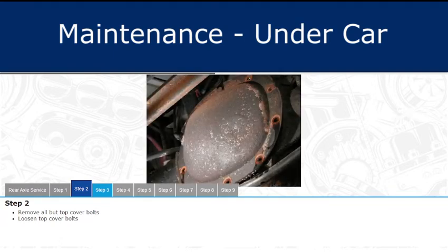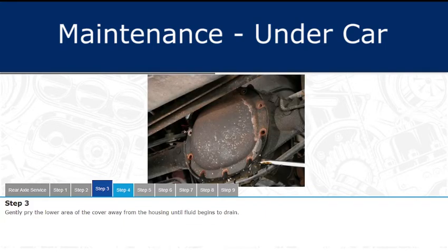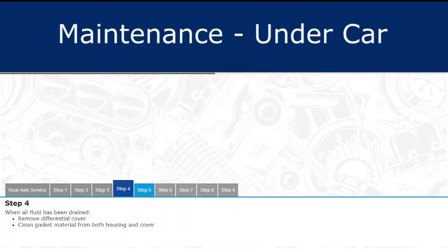Remove all the bolts from the differential cover except for one or two of the bolts at the top of the cover. Loosen the top cover bolts. Gently pry the lower area of the cover away from the housing until fluid begins to drain.